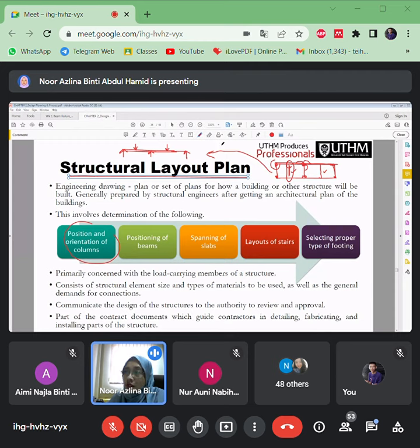If this first step is done wrongly, your calculation will be wrong. You have to know which load applies. Is it a uniform load or a point load? This beam has its own self weight along this line. It also has a brick wall along this line.